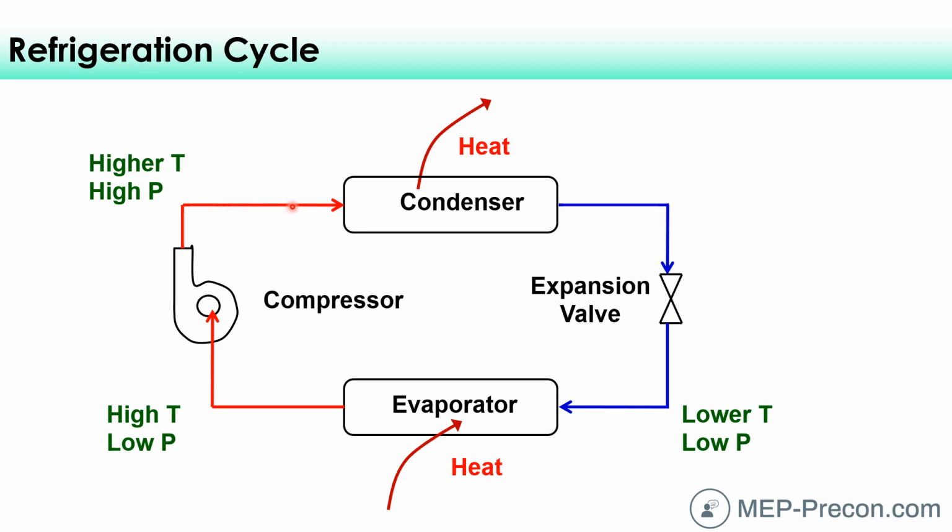And now it's going to go to our outdoor coil. So this coil looks very similar to our indoor coil, except it's going to exchange heat to the ambient air outside. So same refrigerant, it's got those BTUs from our space, it's got those BTUs that are really condensed now at a very high temperature, because we haven't really done anything to the heat. We've absorbed the heat. We're just changing the temperature of that fluid by increasing the pressure.